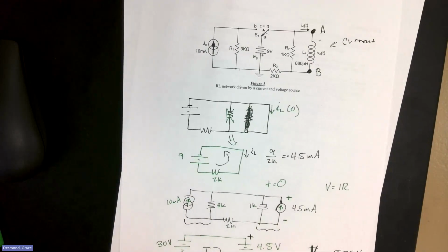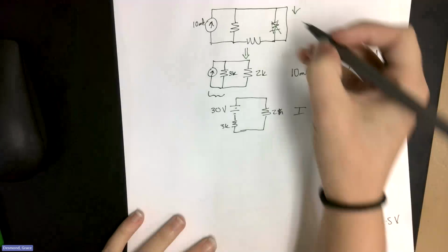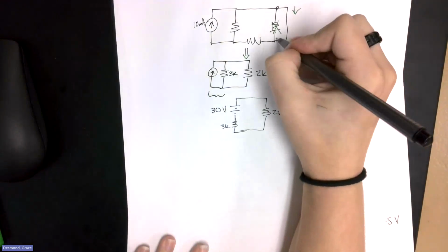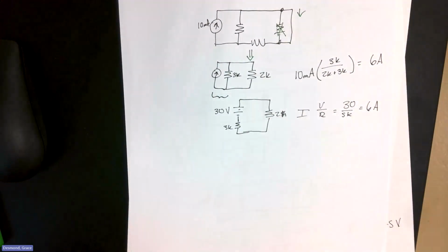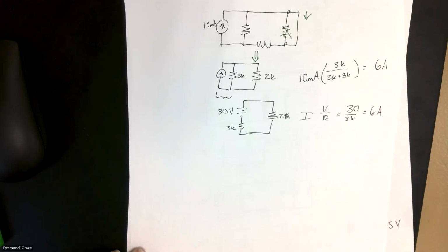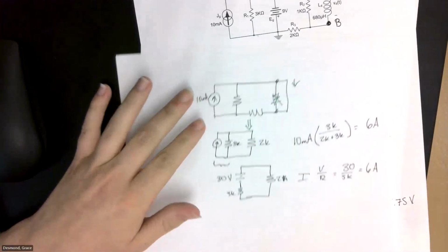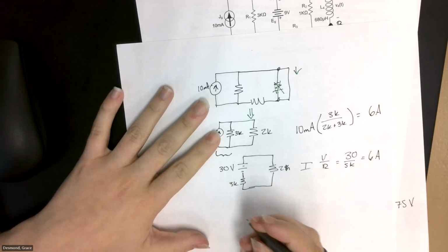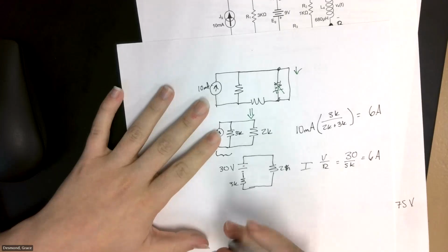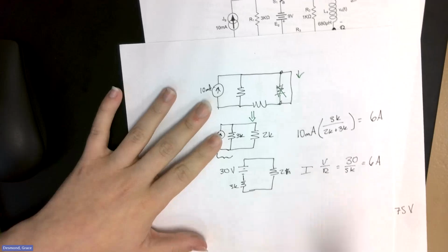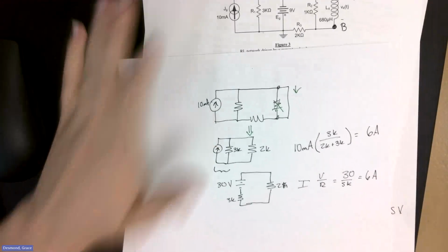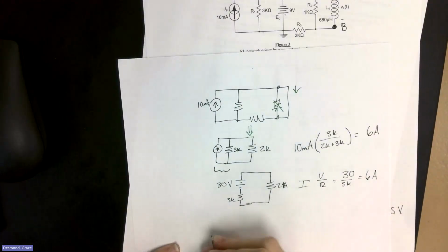So that's why you're always going to do it after the switch flips. So we'll come back over here. We'll draw it one more time, except instead of a wire here, we're going to have terminals. And we turn off the voltage and the current sources. So in this case, what does this end up being? 0 amps, no current, no wire.